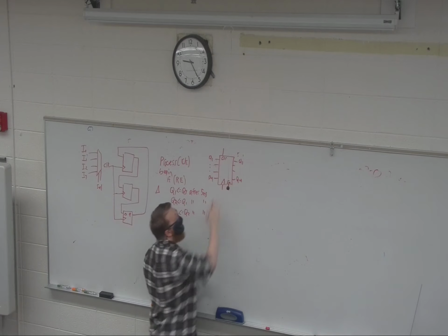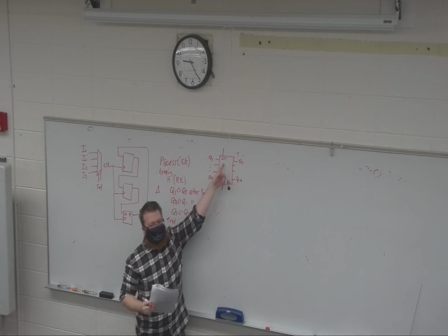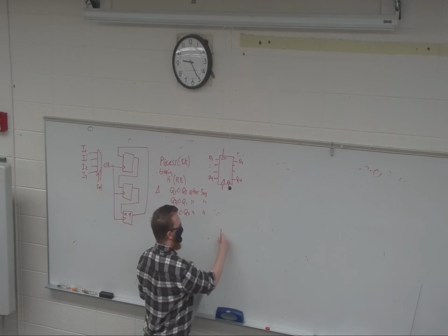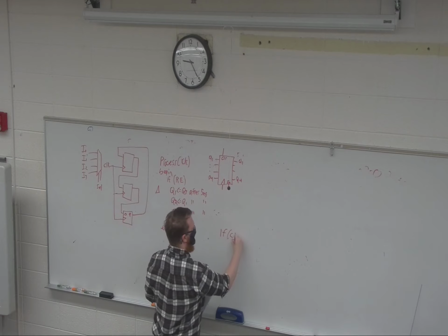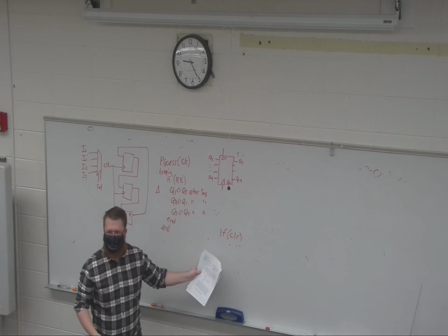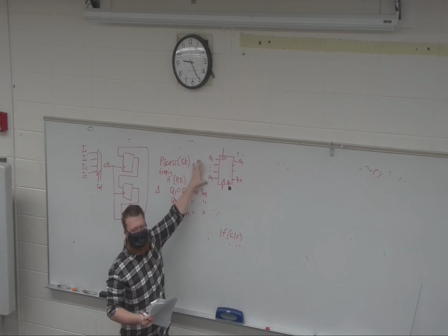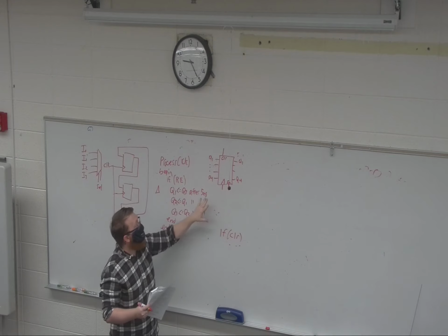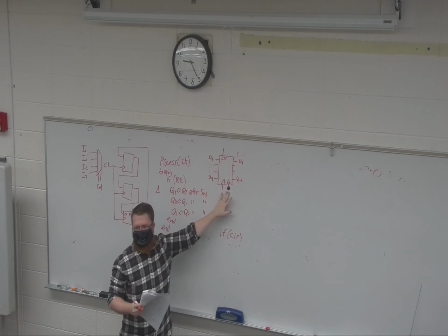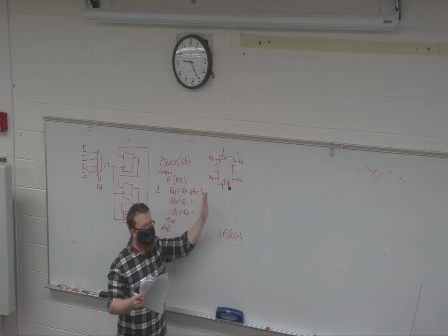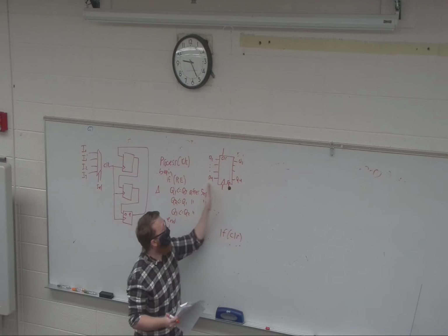if clear. So if I want to clear it, I want that to be the first thing. So my first if statement in this block is going to be if clear, delete the memory, because I don't necessarily want to always remember it. I want the option to get rid of it. Then else enable, another term that they'll use for it is load. So if load and clock, then Q equals D.